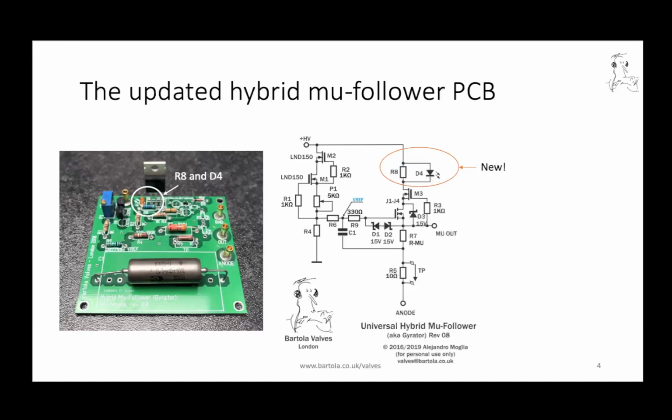It also doesn't affect the stability of the stage unless that resistor is of a very big value. Generally, the M3 is stable enough. We're talking about resistance values of 100 to 200 ohms at the most, and that's not a problem for the MOSFET.